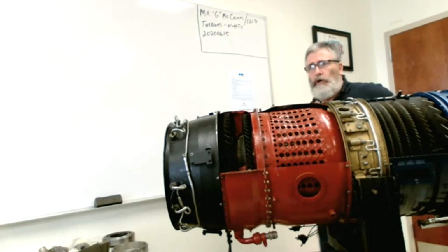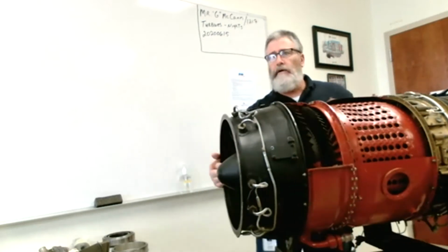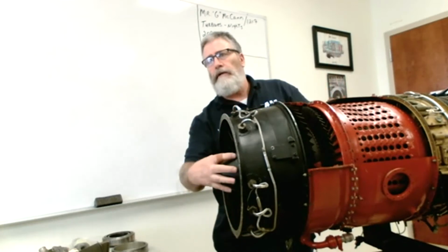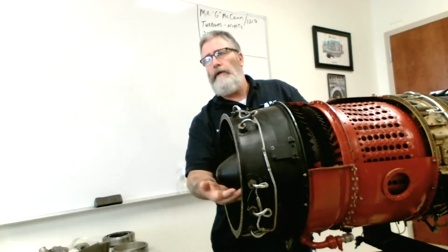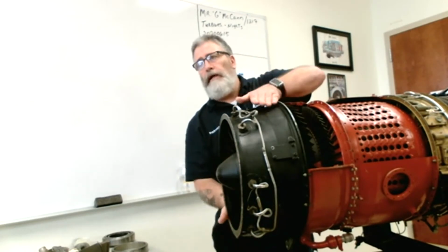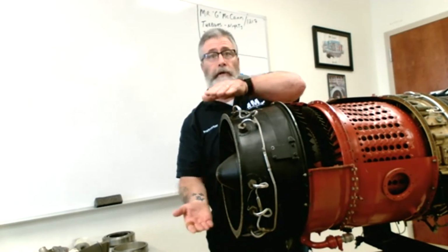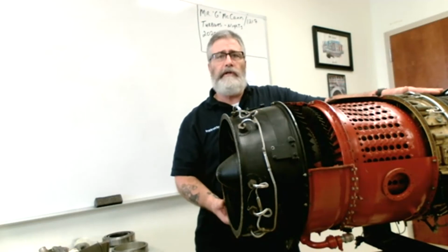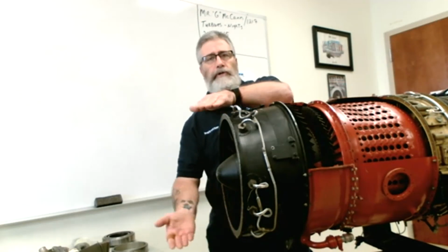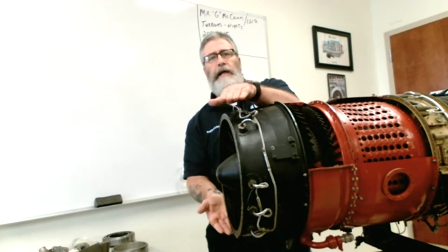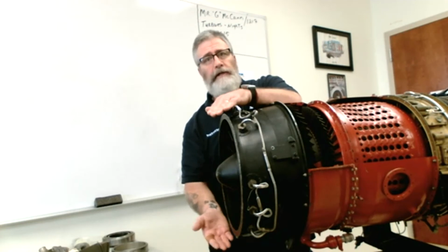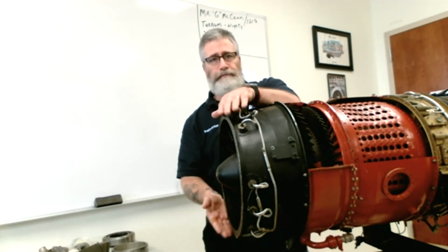So, on exhaust sections, on subsonic aircraft, right? Very specific there, right? You can see that the shape of the exhaust nozzle in conjunction with this exhaust cone, or jet nozzle, or jet cone, forms a convergent design, because as we said, the divergent decreases velocity and increases pressure. Now we're trying to produce thrust, so the convergent characteristics actually decrease pressure and increase velocity. And that's what we're all about. That's what we want to do.